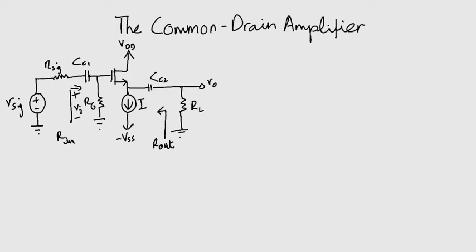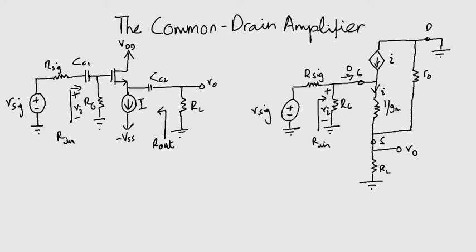Now, in order to carry out the small signal analysis, we need to construct the small signal equivalent circuit. So, any guesses for which model should we use, the T model or the hybrid pi model? Note it down with you and let me make the small signal equivalent circuit. Yes, we employ the T model. Why? Because RL is in effect connected in series with the source terminal of the transistor. Therefore, the T model is more convenient to use.